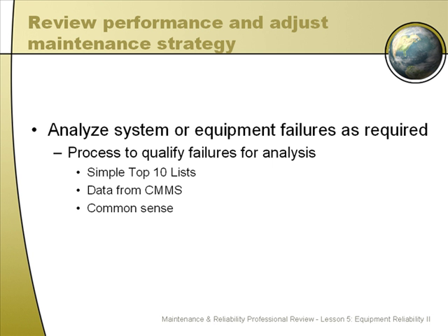Another aspect is to analyze the system or equipment failures as required. Doing analysis is what you do after you identify the gaps. So let's develop a process to qualify failures for analysis. Obviously, it's not going to make sense to run every single failure that occurs on a given day through analysis. It would just take too much time and the payback would be too low.